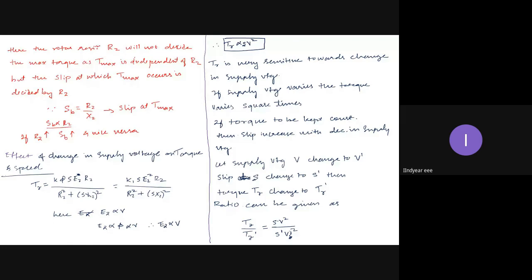They are actually balancing the slip so that the torque developed at all the points is constant. Because supply voltage is constant, I can't change supply voltage there, it is 415 volts. The torque requirement is constant. So what are they balancing there? Out of this relation, torque required should be constant, voltage applied is constant. Now what is the only thing that I can balance? Slip.